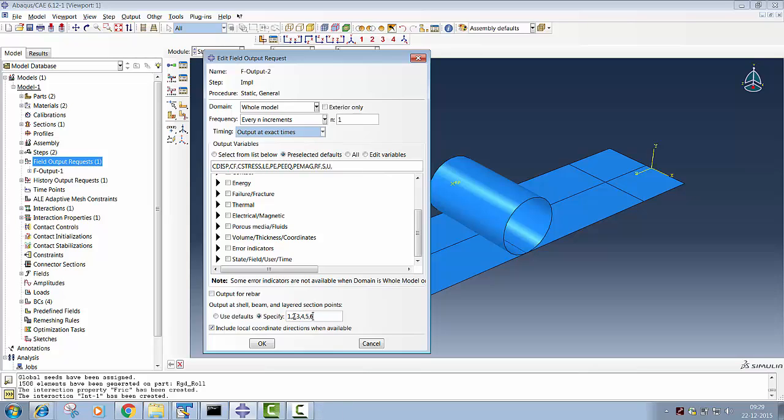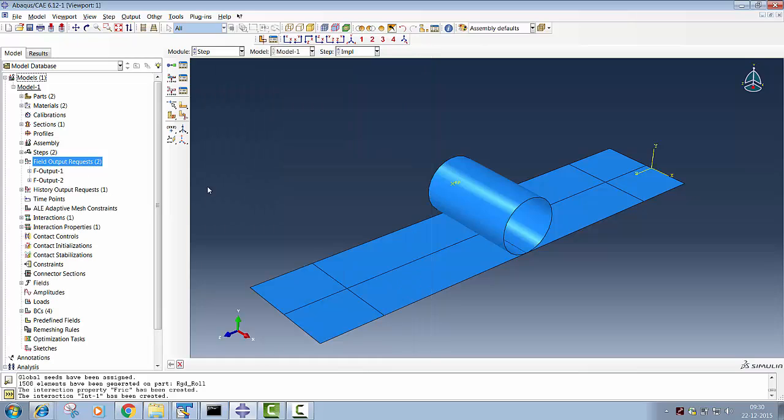This is for the aluminum, and then followed by the steel layer. So once we post process the result, Abaqus will give us the result for all these integration points, so that with these values only we are able to find the through thickness bending stress. So this is very important. So just say OK. And if you define 5 integration points for each of the layers, then you have to go ahead and define all those integration points if you are interested to see a more detailed profile.